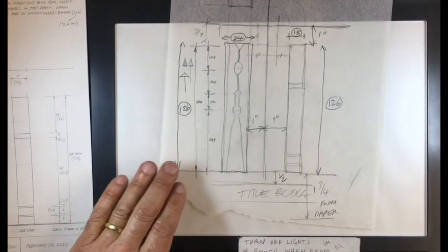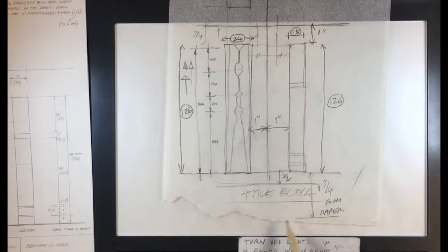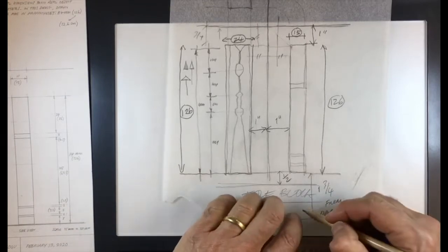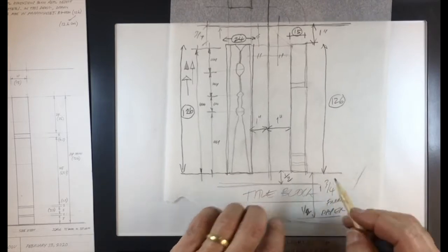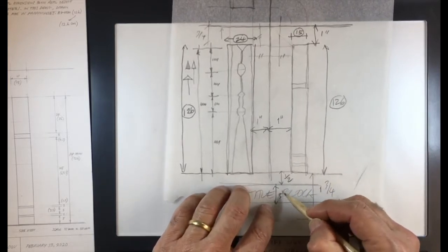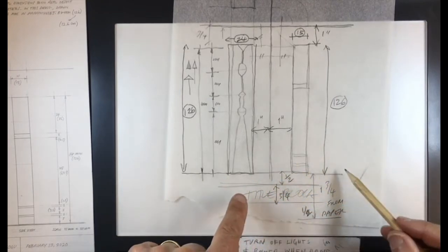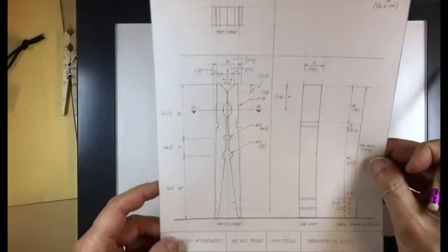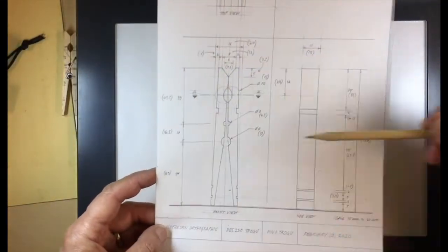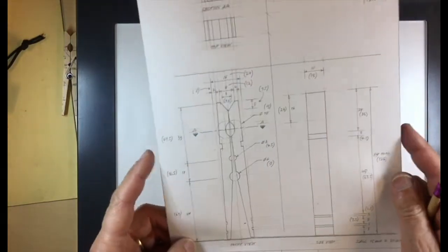Okay, can you all see it? So we have the paper. Half inch from the paper is the title block, which is 3/4 inches. And then we're going to do another line, half inch on top of that. Find your center to put this line in the middle of your drawing. I had to cut off my borders because I had to scan it last night and I couldn't fit it in my scanner.